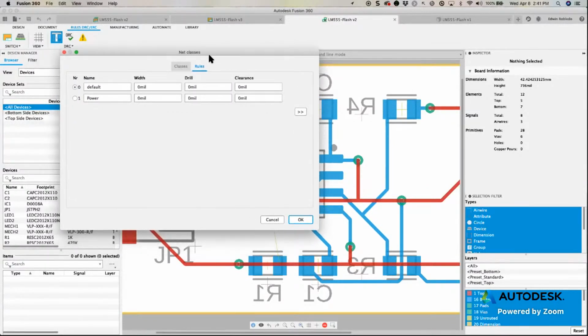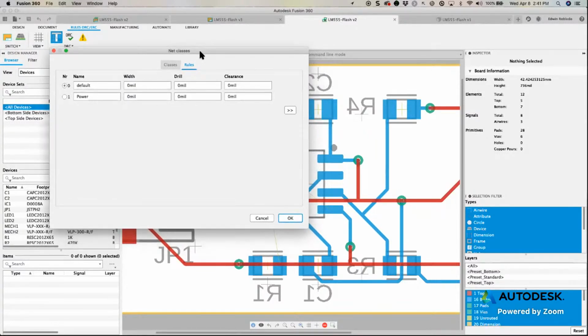Correct, and you see that in the default net class, which is very important. You notice how it has everything set at 0. Basically the DRC and the net classes are always working together. The larger of the two is going to win. So by setting the default net class to all zeros, this guarantees that by default, the DRC is in control.